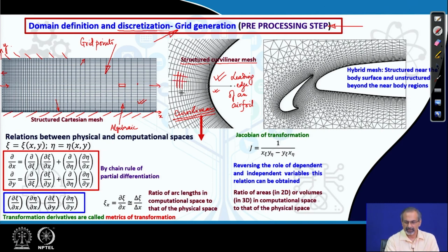And therefore, if you pick up any point, any grid point which is formed by the intersection of these lines, then you can find only one line from each family which crosses it. So, one line from this family and one line from the other are crossing that particular point. So, each point can therefore be formed by crossing of one line from each family. That is basically what we have in structured grids.